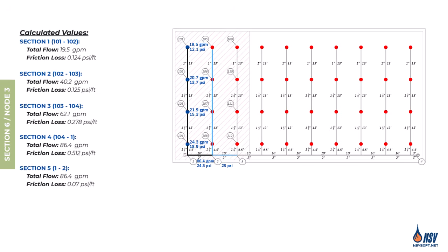To calculate the flow rate of the second branch line, which includes sprinklers 105 to 108, we apply the concept of an equivalent K-factor. Since both branch lines are identical in terms of pipe size, pipe length, C-factor, sprinkler type, and number of sprinklers in the design area, we can use the same equivalent K-factor from the first branch line.